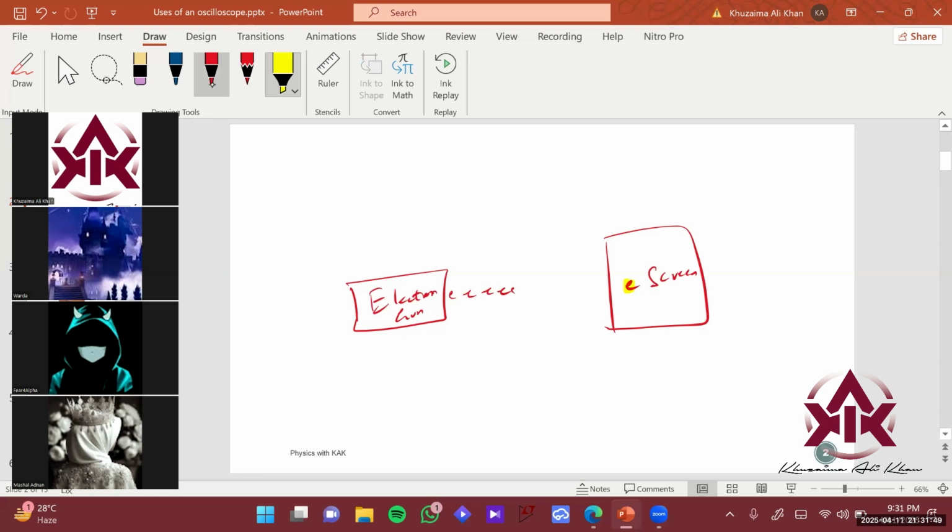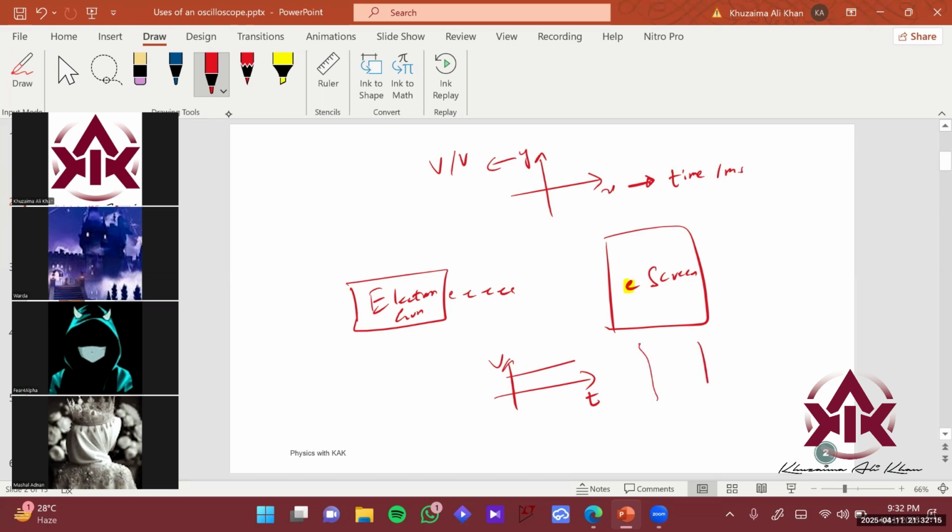So it has two settings, it has two motions, it has x-axis and it has y motion, right? So this is basically used to show time, right? It shows time in milliseconds, and this y value basically shows you the voltage level in volts, right? So you can basically adjust these settings to display different types of waveforms. You can display DC waveforms, right? Which is time. This is V. You can also display AC waveform, right? Depending upon your input. And you can also display just a spot here, okay, which depends upon your different type of settings. We will explore all of those scenarios in your lecture.